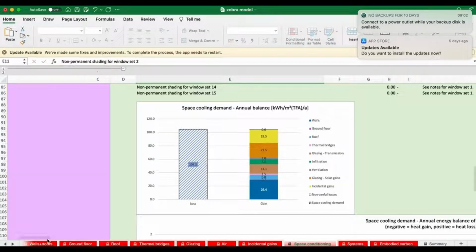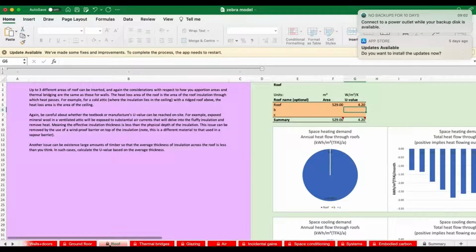So the ground floor is the purpley one, and that's small, so we're not going to add any extra insulation to the ground floor. That we can kind of conclude would be just a waste of money. So let's go to the roof, and this is going to have the biggest impact, isn't it, on the apartment that's adjacent to the roof, which could have a huge air conditioning load at the moment. And we're going to insulate the building. We're not going to go for passive house or anything particularly fantastic, but we're going to put an insulated layer in there, and you could look up ways of doing that within this context. But imagine we've done that and we can get to 0.35.